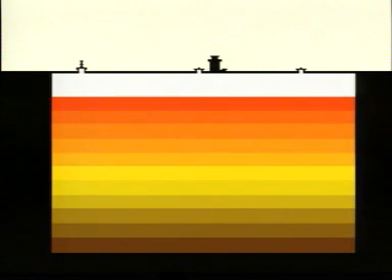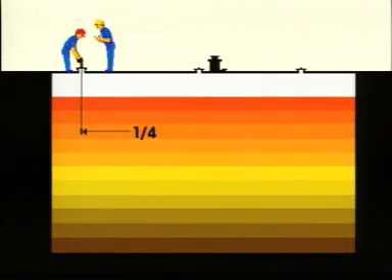After a long sea voyage, there will be layers of different temperatures in the tanks. Every tank should be measured and calculated separately. Measure the temperatures to the nearest half degree. Here we use the multifunctional MMC instrument, this time set up to measure temperature. Temperatures are taken at 3 different levels: a quarter, a half, and 3/4. Depending on equipment available, the routine may be different on your ship.